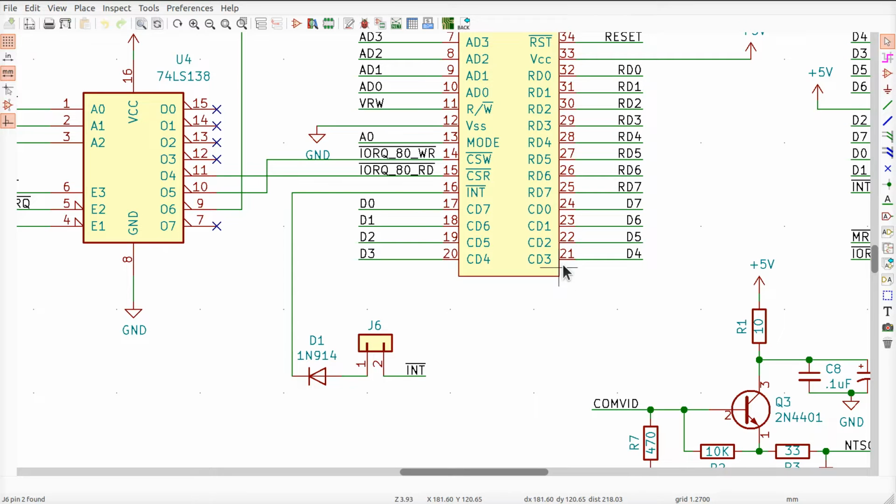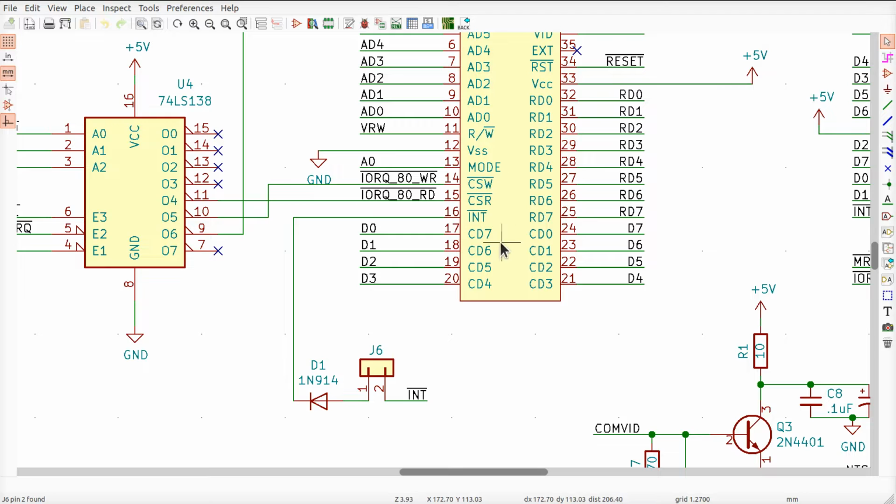You either say everybody generates an interrupt and I don't care who it is and I have one handler for everything, and then you get to play needle in a haystack to figure out what happened, or you use something like a different mode where there's a handshake and a dialogue that takes place between the Z80 and the peripheral device, which this thing is unable to do. And the device can then say, hey, I'm the one doing it, and will you please call my subroutine instead of the other ones? And then the Z80 can use what we call a vectored interrupt.